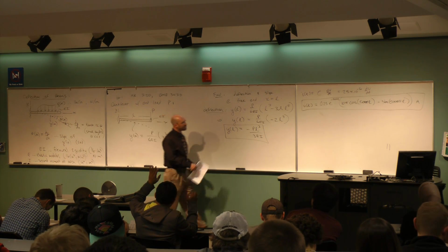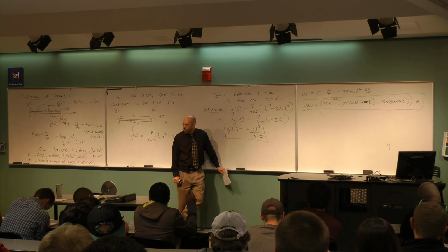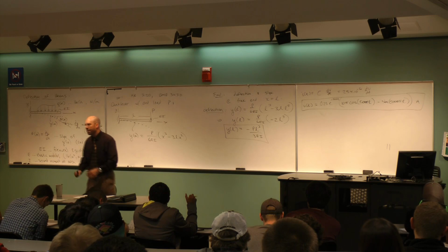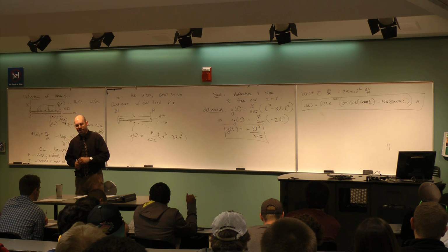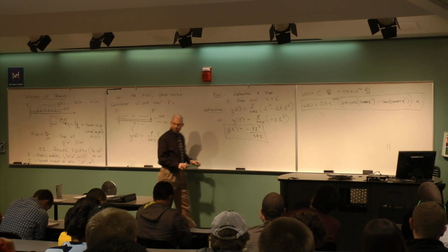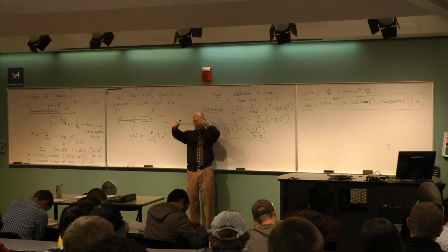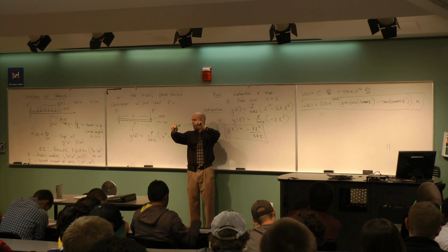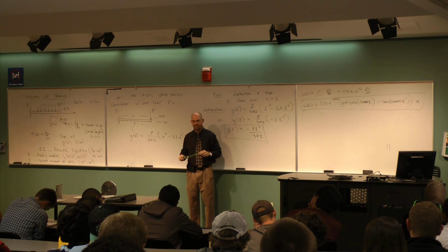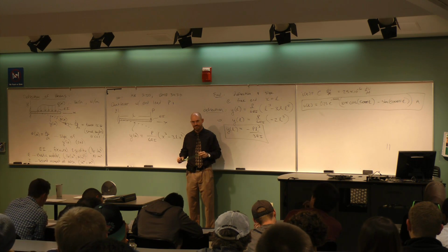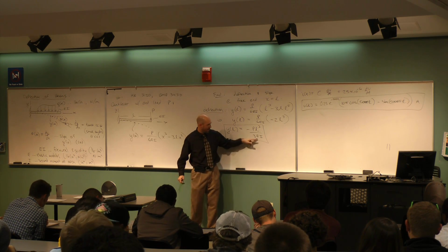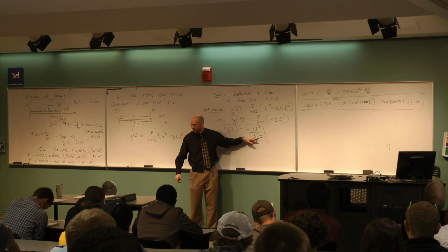So for example, if I want this thing to deform half as much, what's a better thing to adjust? The material, right? Try and get a new material. If I want it to be half as much, then the E value would be how much bigger? Twice as big. So I need to find a material with twice the stiffness. That'll take care of it. I put a 2E down here, I'll get half the value.